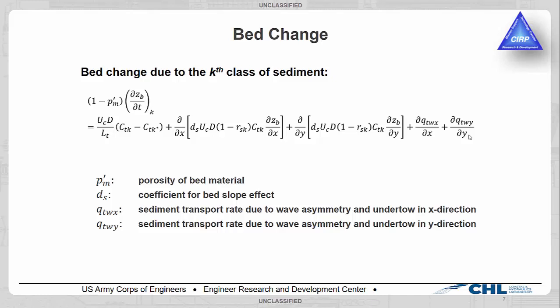Also there's a coefficient for bed slope effect here, ds, contained in these two terms. ds is also a very important term for model calibration, and as you can see in the equation, it mostly controls the bed load transport.